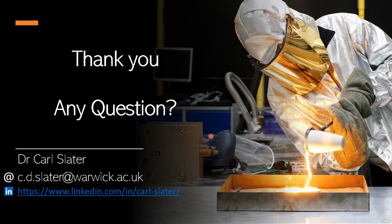So if we're talking about the actual Gleeble testing, then the plane strain setup that we have in the HTS doesn't actually require any lubricant or any interface there at all, because the HTS works slightly differently. For those of you that don't know the HTS too well, the electrical load comes through a different axis than what the mechanical load does, as opposed to the 3800 where you have the same contact for electrical and mechanical.